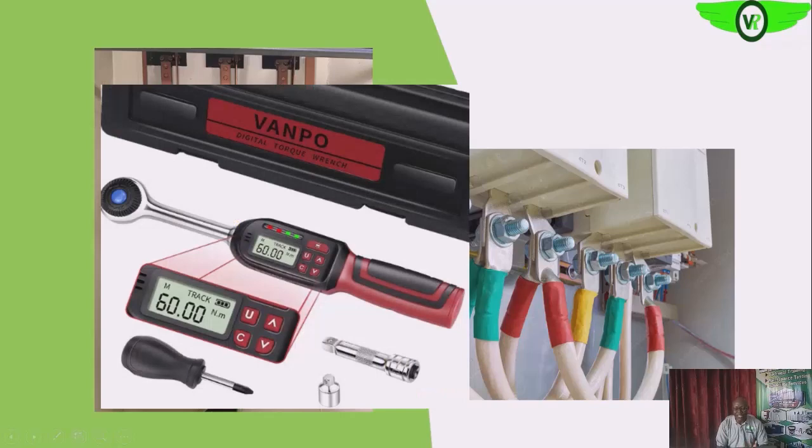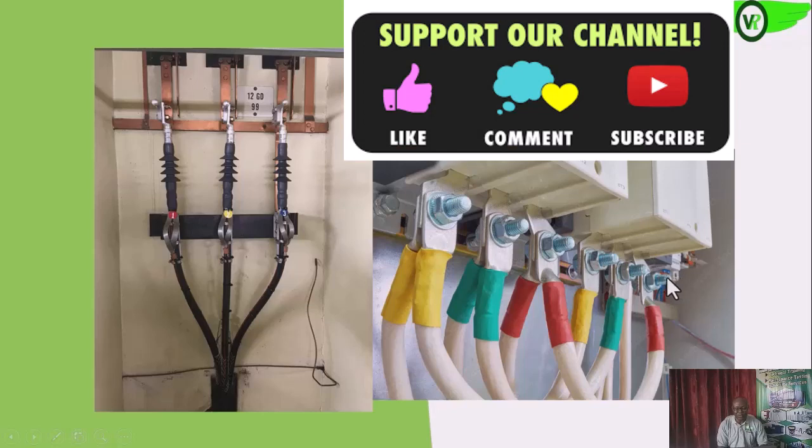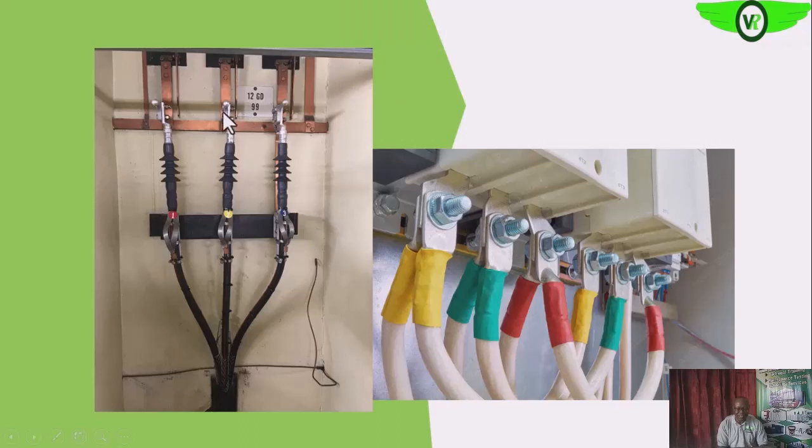So in using that calibrated torque wrench, you need to torque it to the level that is specified by your facility for these terminals. Okay, so if this is an equipment, the equipment manufacturer may specify the torque level to which you can drive these nuts or bolts. So you have to drive all of the terminals of the connections to those torque levels.